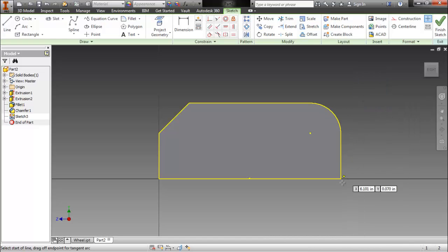So I'm going to create a line, and it automatically snaps. When it turns green, it normally means halfway mark, parallel, perpendicular, etc. So right here, it automatically snaps to the corner. I give it one click, type 1 inch, and as you can see, I can control my angle. 90 degrees is straight up and down, or I can just drag it around until it clicks into position. So 1 inch. Now I'm going to do 1 more inch, another 90 degrees. Right there. I didn't type anything in, it automatically snaps. I go ahead and click escape, and it gives me this point right here.